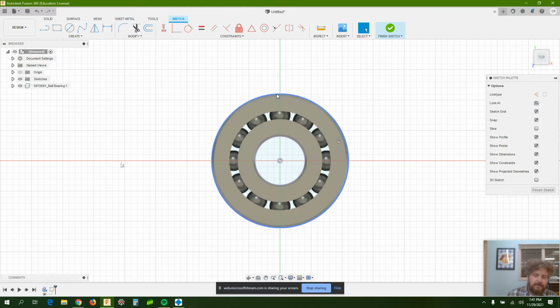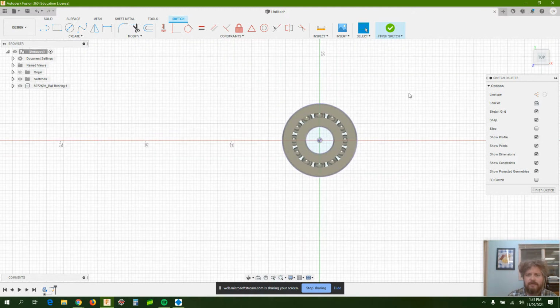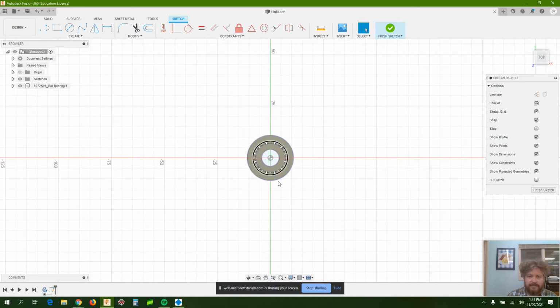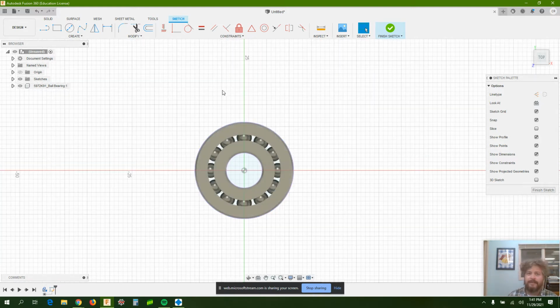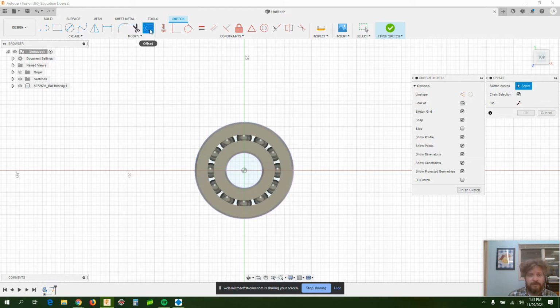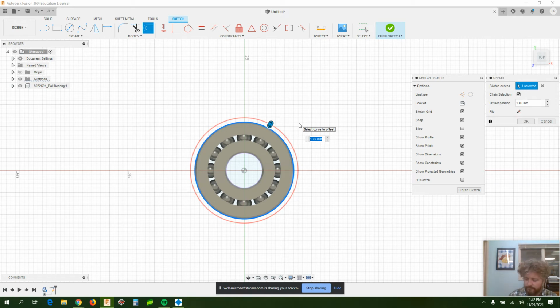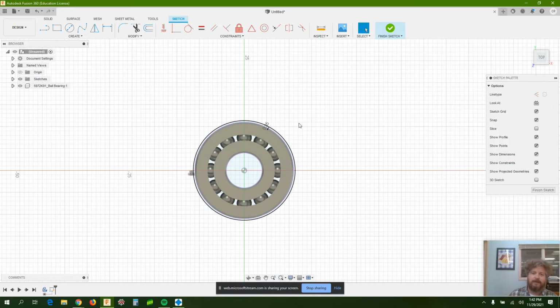What do you do with that? So you could then use this circle to create your object, your spinner here, because that is now the inside diameter of my fidget spinner. But you know, like I know, that there's an issue here. When you take two things and they're the exact same size, they're not going to fit together. So we want to use this offset tool to create a circle that's slightly larger. Let's say 0.35 millimeters larger. And that'll leave enough clearance for the 3D printer that is making your fidget spinner to have a little bit of an error, and maybe the manufacturer of the bearing itself is not going to be perfect.